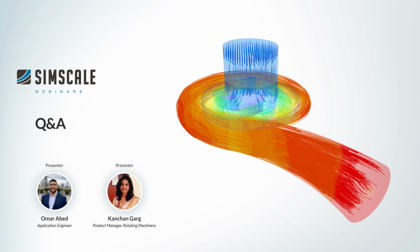Yeah, that's a good question. The nature of simulation is always going to be, there's always going to be some margin of error working with models that are not necessarily designed for production and don't have the clearances and seals that you may have in your final design. But aside from that margin of error, we're usually seeing 2, 5, 7% margin of error between test data that is generated, excluding external systems like the motor efficiency and such, to the actual simulation data that we generate within SimScale.